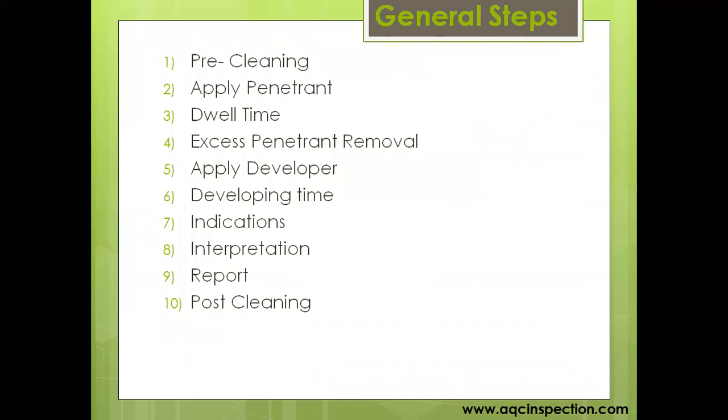The general steps for liquid penetrant testing are pre-cleaning, application of penetrant, the dwell time for penetrant, excess penetrant removal, application of developer, developing time, indications, interpretation, reporting, and post-cleaning.